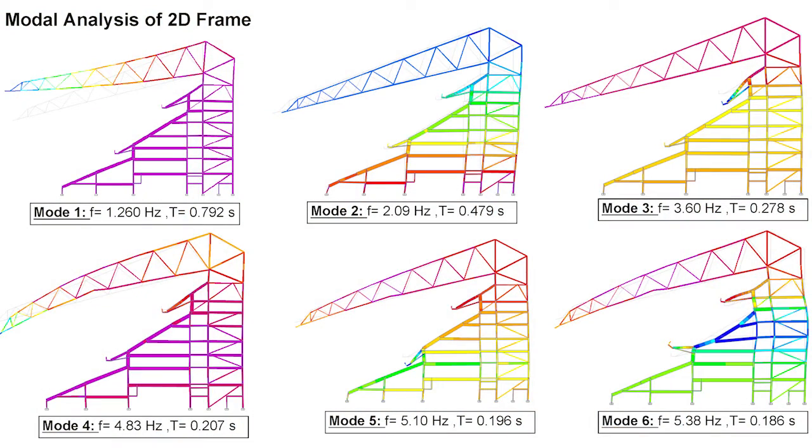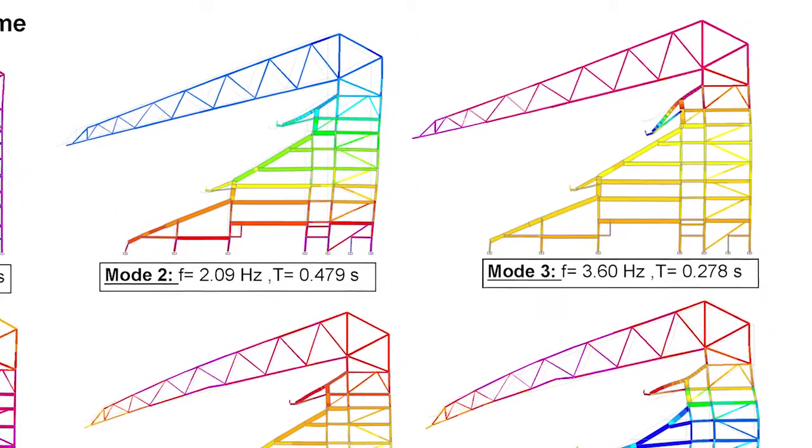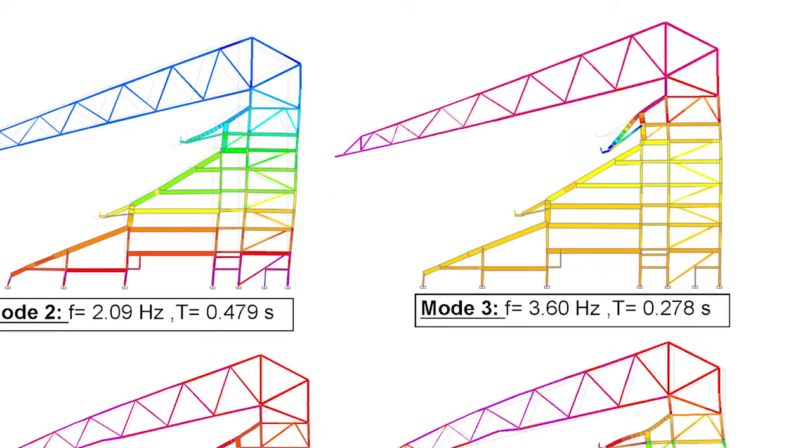An example we've done for a Premier League club, they were asking if they can host concerts during the off-season period. What we've done, we started with the 2D analysis of the stand to realize which mode could be excited by the crowd. And then we found that the 3rd mode is the one that could be excited by the crowd, but it has a frequency which is much less than 6. It has a frequency of about 3.5 Hz. And that meant that we had to go through the complex dynamic analysis of the structure.